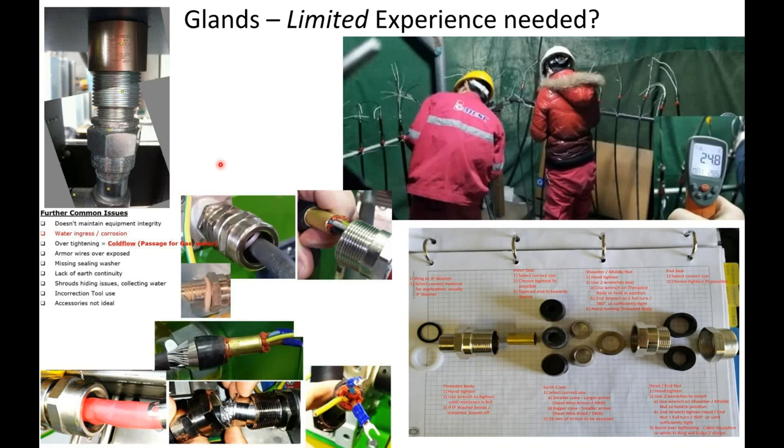Within the industry, interesting thing is that 80% of our non-conformancies on a project during the installation and commissioning phase, I should say installation and mechanical completion phase, is glanding and terminations. Now, anybody with a lot of EX experience, not everybody will know this, but when dealing with a flame-proof enclosure, and actually most enclosures, you shall only have one adapter or reducer. You should also take into account dissimilar metals.